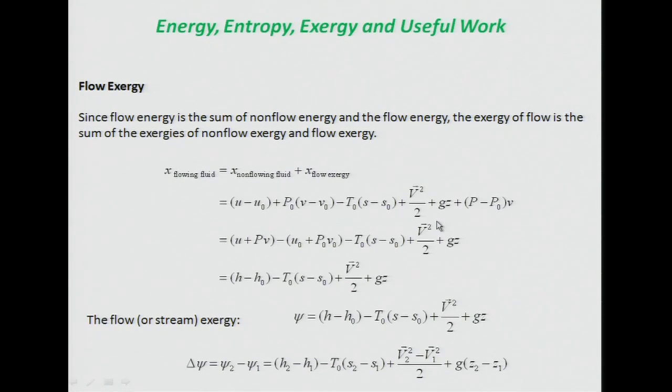Remember, we dealt with that, and we can call it a stream enthalpy. We can use enthalpy in here because we've got these PV terms in here. We can define the specific enthalpy and write it out this way. And what's different then in here is this quantity with our exergy, and it's related to the temperature of the surroundings multiplied by the change in entropy from the entropy of the surroundings.